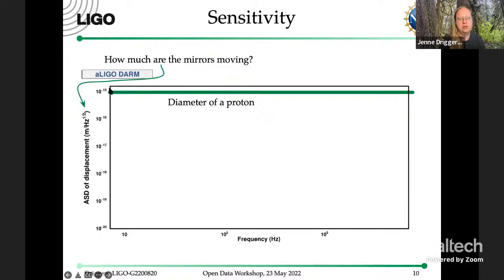So this plot I show, there's no data here yet, just so that we can talk for a moment about what it will show. On my x-axis, I have frequency. I know that there's been some chat in the chat window during Martine's presentation about what kinds of FFTs and stuff we can use. So that's one thing we do when we're looking at the noise performance of our interferometer. We do an FFT using Welch's method to look and see what amplitude of data we have at each frequency. So we usually look between about 10 hertz and a few kilohertz.